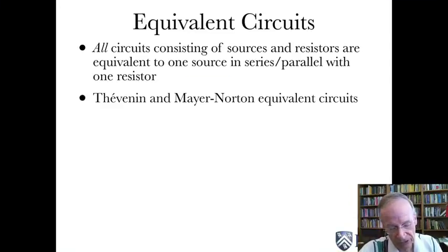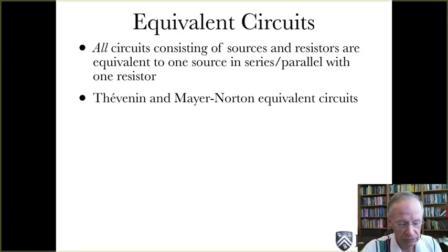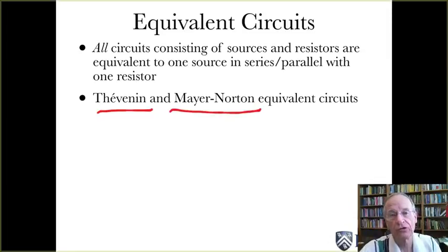So that means that we can use either of these equivalent circuits, the Thevenin or Norton form, the voltage source or the current source form, whichever seems to be appropriate, that makes solving the problem easy. What I mean by that is you're now going to attach something to the terminals and determine things. And depending on what you're interested in finding and how complicated the circuit is you attach, you would use one or the other.